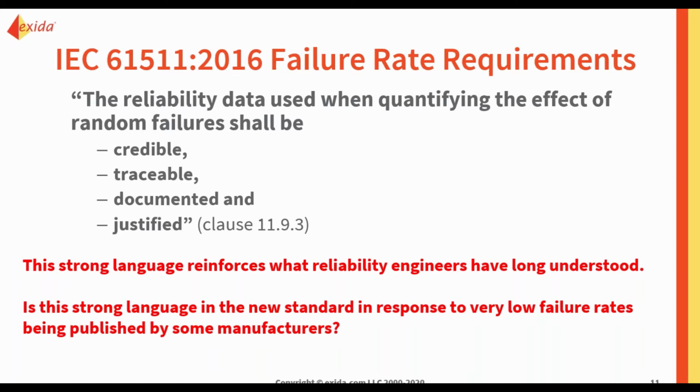But both IEC 61508 and IEC 61511, when they did their newest revisions of the standards, took it further. Instead of just saying this is what failure rates are, they say not only are they what they are, you need to use them in assessments, you need to use them in equations, and not only that, they need to be credible, traceable, documented, and justified.